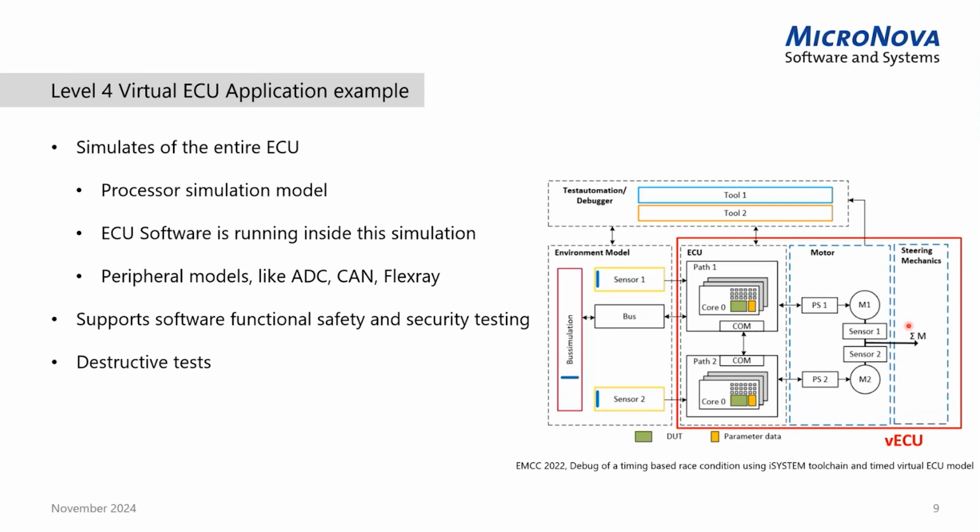And this even higher level of virtual ECU integration allows us to have a little bit different test focus, because we can also focus on functional safety requirements and on security testing, and for example also employ destructive tests that would not be possible on our hardware-in-the-loop simulator without actually bricking the ECU that we want to test. When we think about security features like fuses that are generated in hardware.